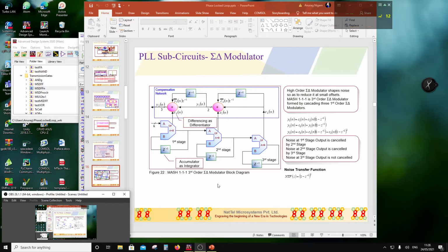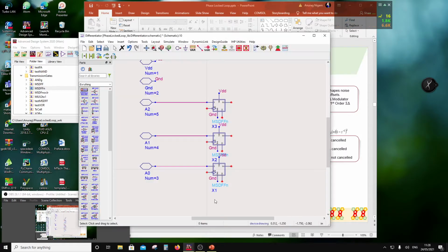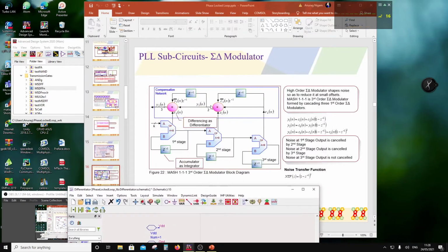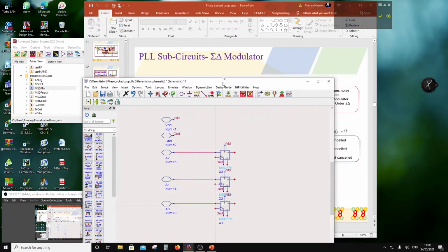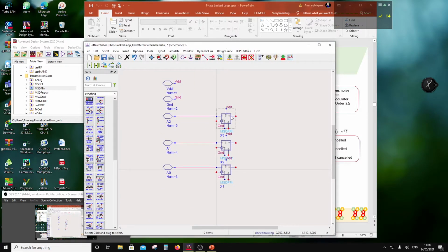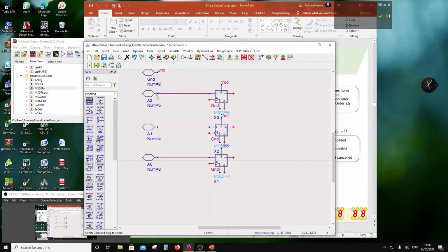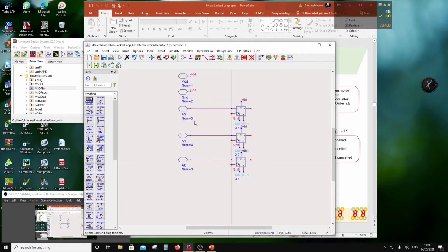So what I need to do here is, first of all, delay it. That is Z minus here. So I'm doing this first Z minus here, delaying it. I have this D flip-flop where I'm delaying it. The next thing is, instead of taking a Q out, I'm taking Q bar. That is going to be the ones complement. So basically this word, which is A0 to A2, I'm doing a delayed copy by Z minus, and then doing a ones complement of this, right?